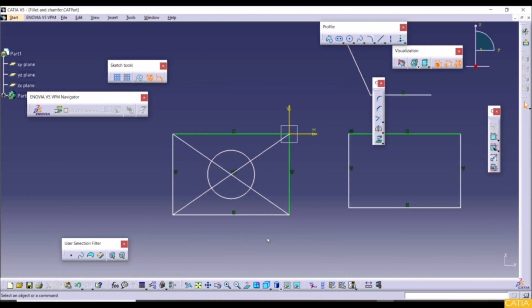But what is the problem now? For example, if you want to project this sketch to 3D model, this is not possible. Because here we have those 2 lines that intersect this circle here. In order to make those 2 lines invisible for 3D projection, we can go here and we can use here construction standard element. So with this tool, we can convert standard sketch elements into a construction element. Construction elements support you to create a sketch of a desired shape and size.